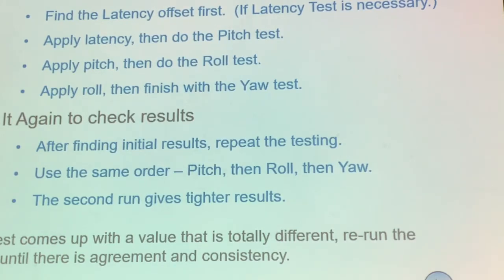It should be between minus 5 and plus 5 degrees. It shouldn't be more than that. If it's more than that, it means there is something wrong with the way you did the patch test. So minus 5 to 5 degrees. So latency test first.